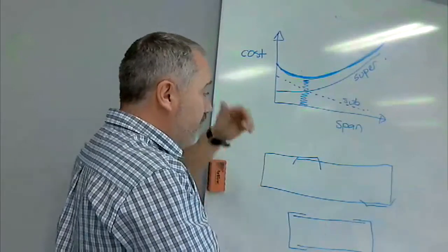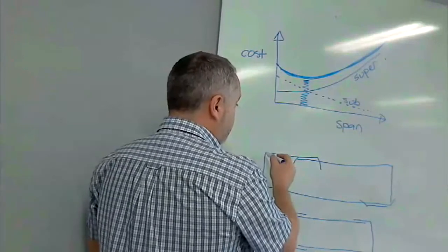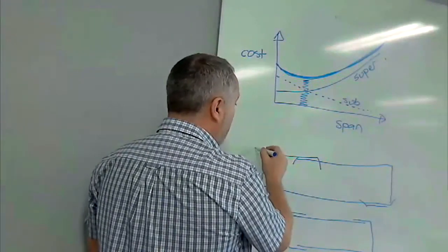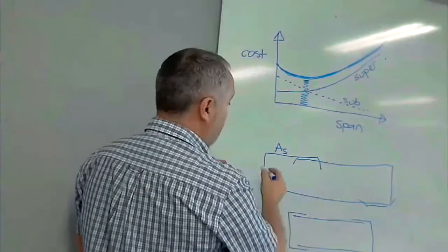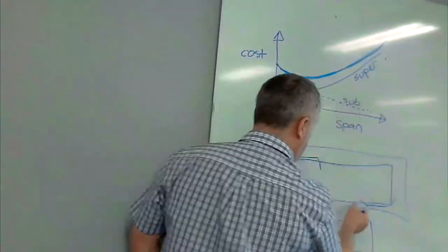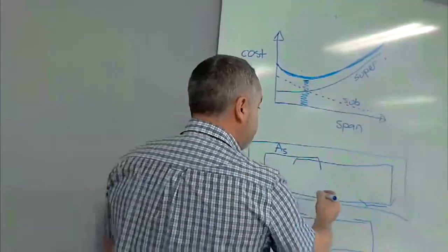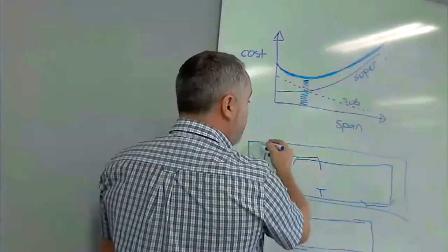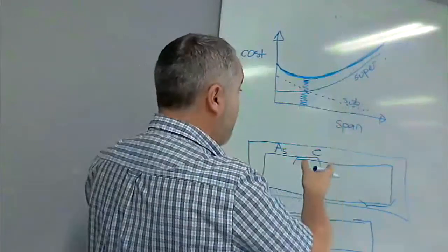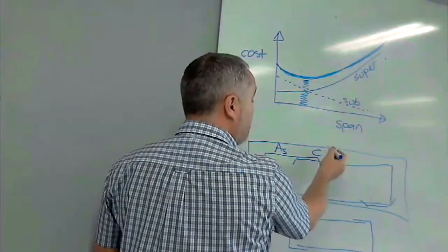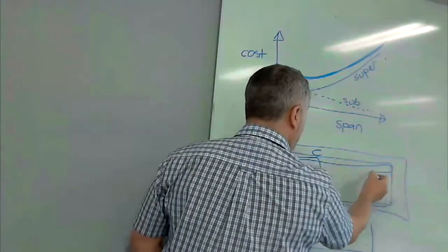When you come to do reinforced concrete design, what's important is the area of steel that you've put in at the top and at the bottom. With concrete, the steel at the bottom is coping with tension, and your concrete is coping with the compression. But if the load coming down is going to create too much compression for the concrete, then you have to add steel in the top.